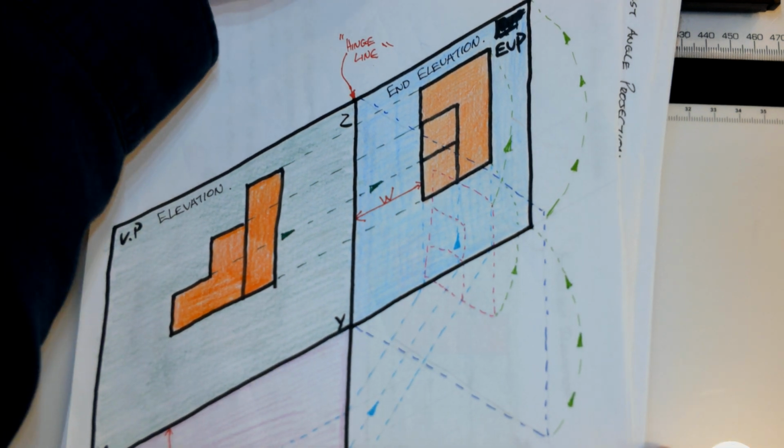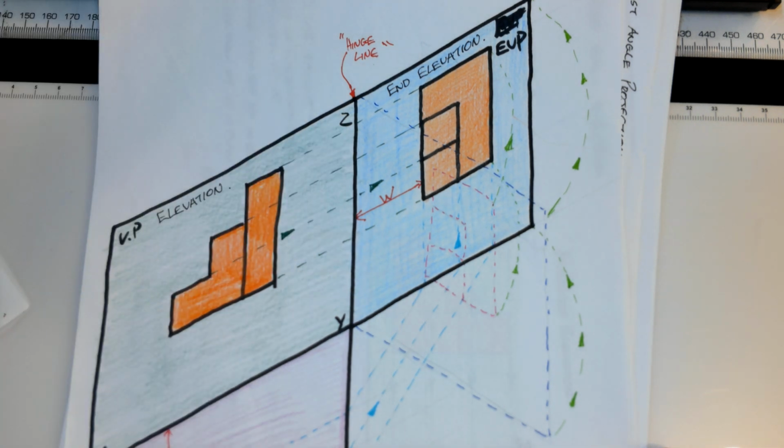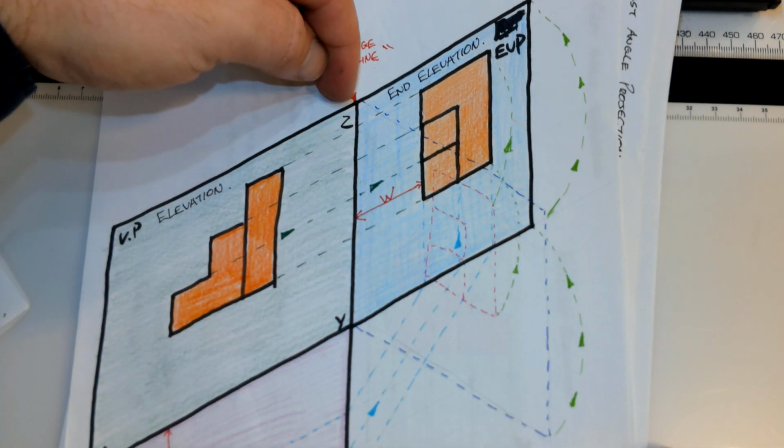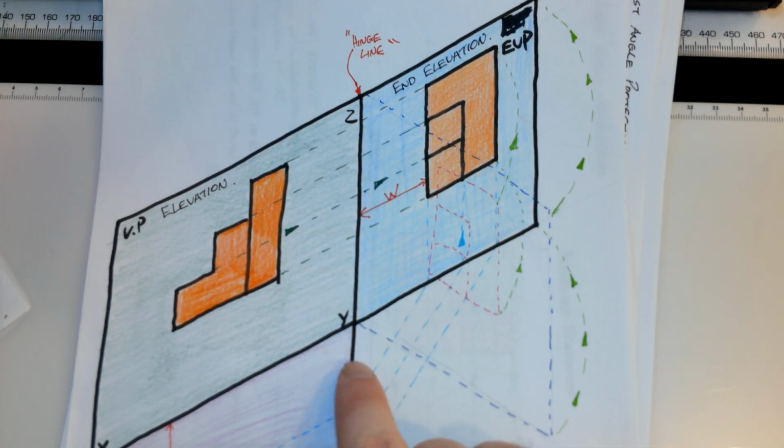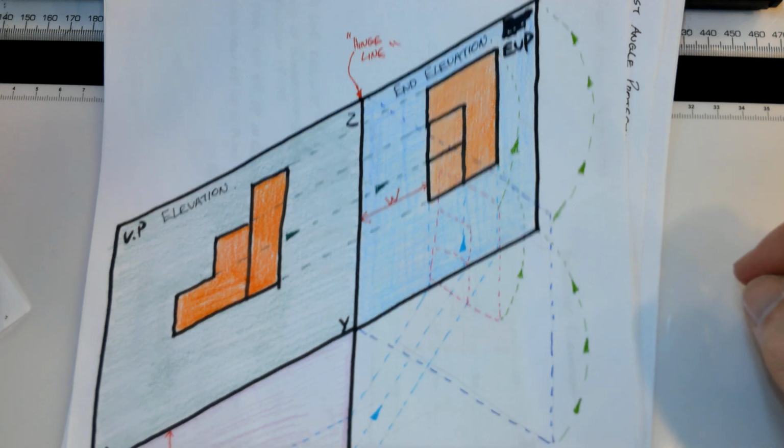Now if we imagine looking straight down, what we will see is we're going to see a hinge line. So if we look down this ZY line, we're going to see a dot. Imagine it's your door looking down from the top. It's going to swing open. And what that looks like on our sheet is this.